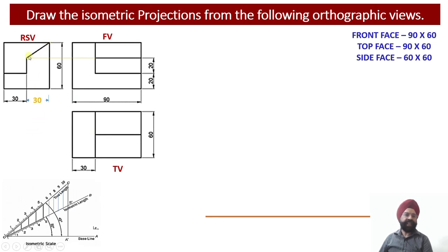Please see. This inclined segment is going to give me this rectangle from the top view. So in the top view, this is the apparent shape of this surface. Why is this the apparent shape? Because this happens to be an inclined surface. If I am looking at this surface from the top, the projection of this inclined surface in the top view will give me this particular rectangular shape. So even though it may appear to be a simple rectangle, this rectangle has been obtained corresponding to this inclined surface over here. So this is the inclined surface.